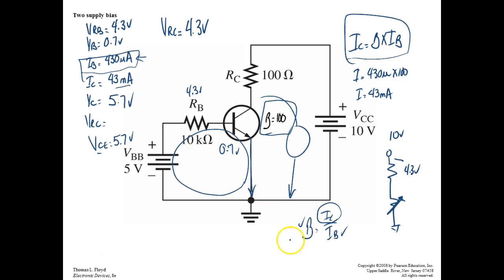So if I know this formula, then I can come up here and develop my equation thing, where I say beta is equal to IC over IB, and I just cover up what I want to solve for. What do I want to solve for? IC. So what's IC equal to? It's going to be equal to beta times IB. Now, where did you all learn these rules? Where did you learn how to do the three expression thing? Ohm's law. You do Ohm's law and Watt's law.